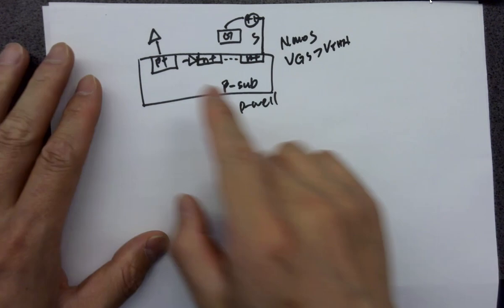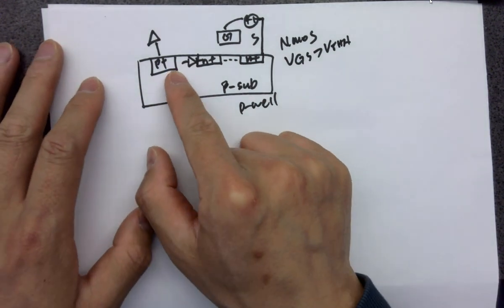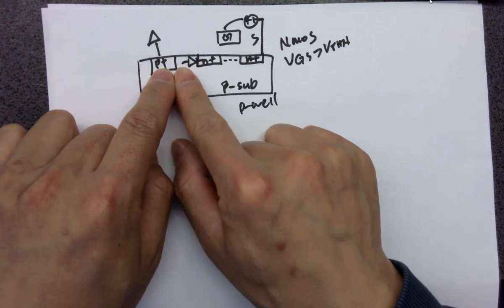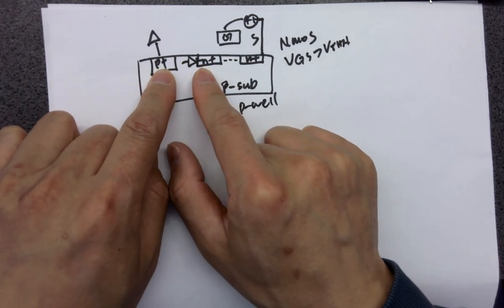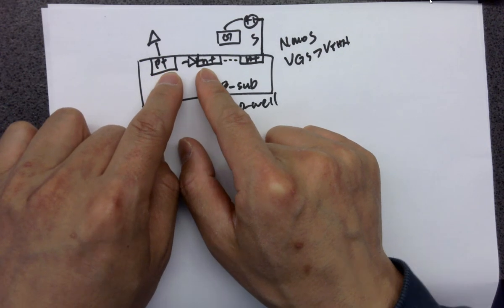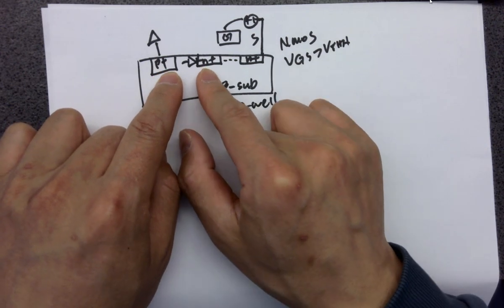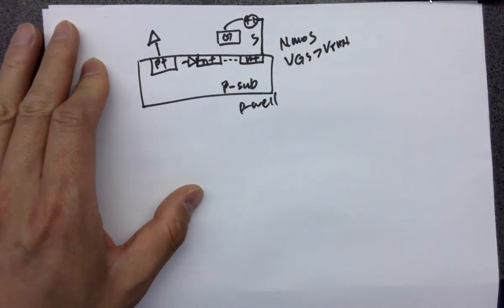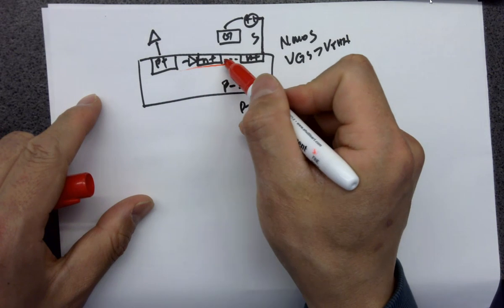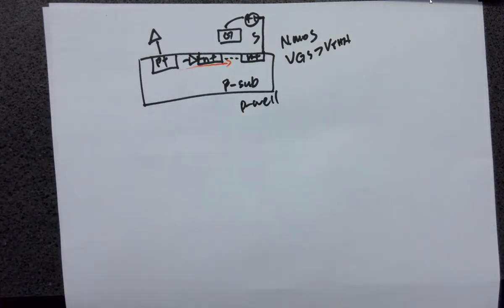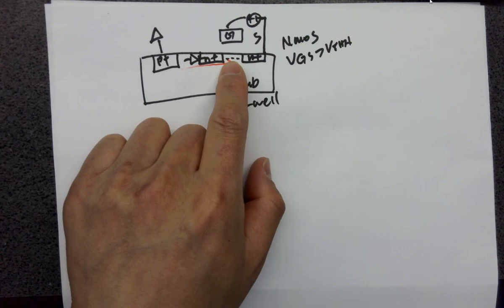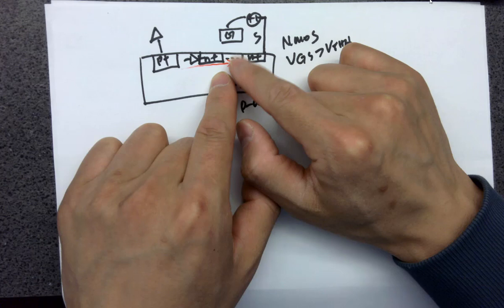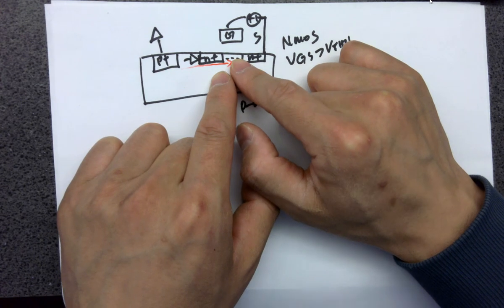Whenever you get a forward biased diode from the well to this node, which means a higher potential at the anode of the diode and lower potential at the cathode, there will be a current flow. Current is going to flow in here, injecting holes into the channel. It's going to cancel all these electrons. So this voltage source has been working so hard to attract all these electrons to turn on the channel, right?